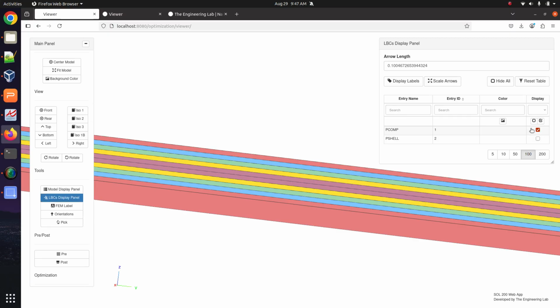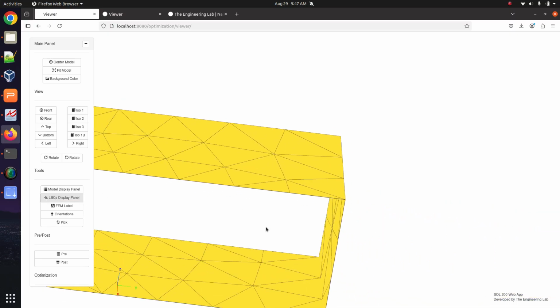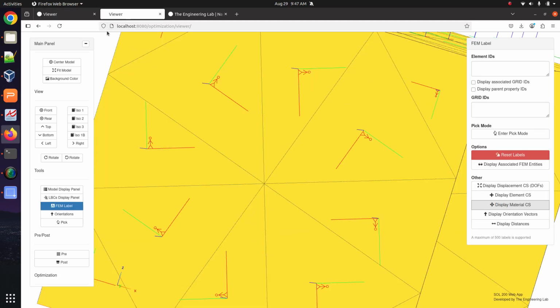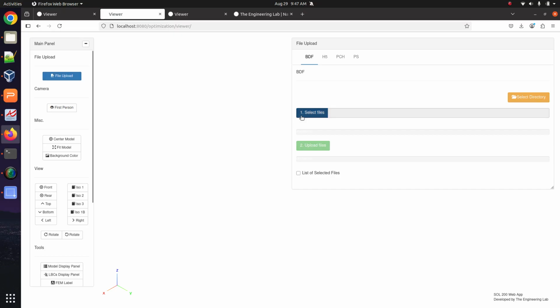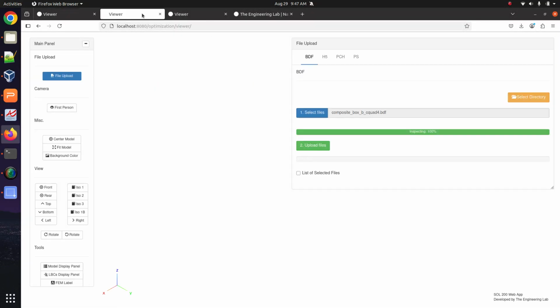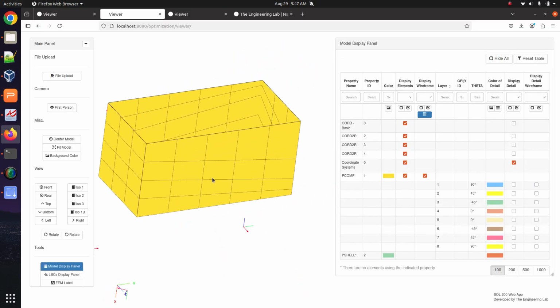And now we have to worry about the direction of the 0 degrees for each element. You have to do this whether it's a mesh with 2D elements, let me just show you actually. The 0 degree direction will matter whether you're using the triangular elements like we did in this window or quadrilateral elements like you see here.